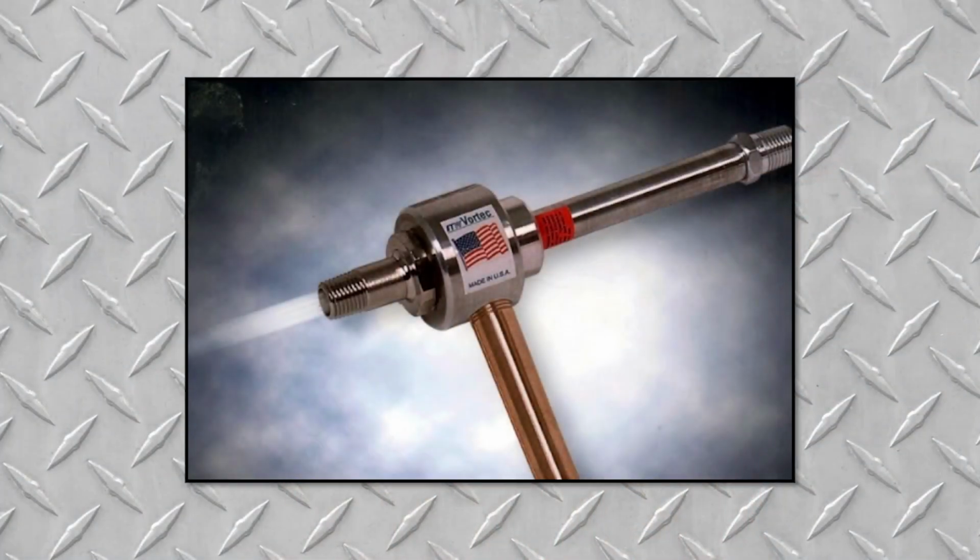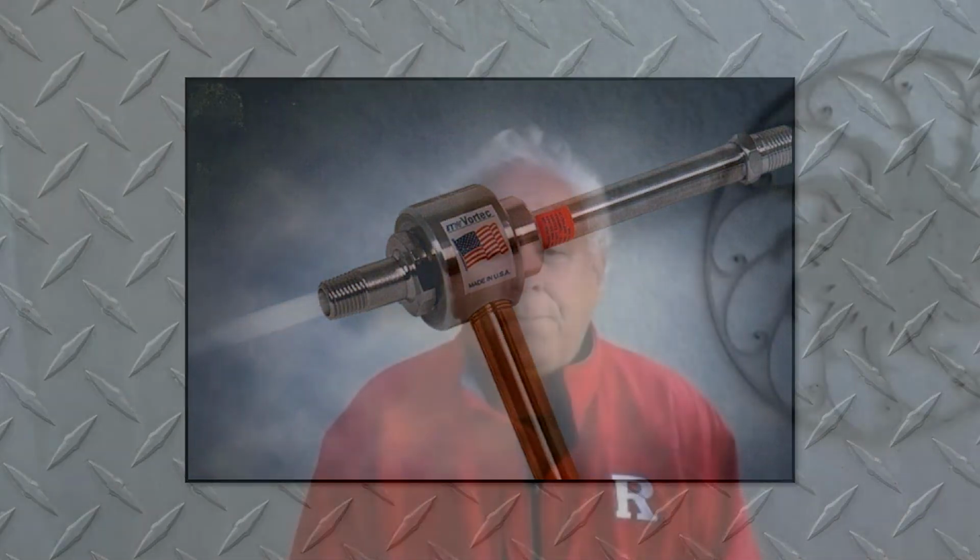You can use something such as a vortex tube, which is a device that uses compressed air that's spun very quickly and creates a very cold stream. This can be used for spot cooling in a process. Let's say you're bending metal and at certain points it's getting hot and you're getting problems with quality. You can use a vortex tube to cool that spot rather than cooling the entire area.